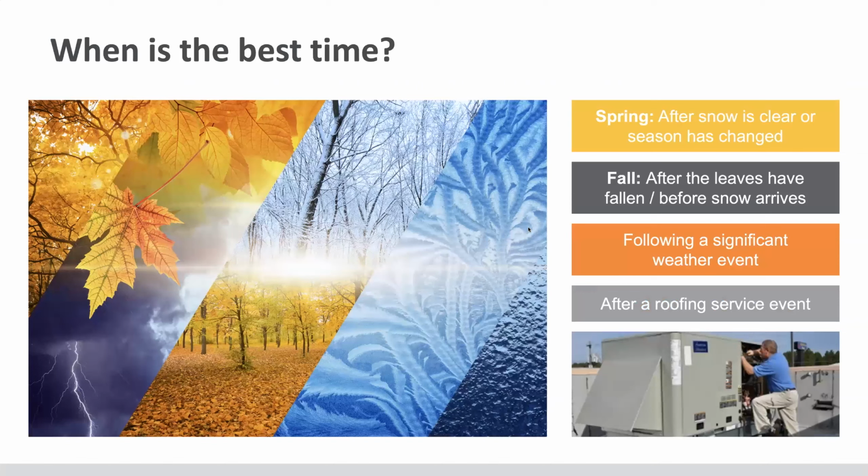The best time we feel to look seasonally is in the spring, especially, I live in northern Wisconsin, when the snow clears, it's really a good time to take a look. Expansion and contraction has occurred, and things tend to pop open, blow up, if you will, and it's good to catch those things on an annual walk prior to the water coming in, those April showers. And again in the fall, if you have snow, before that roof gets covered, clean out the drains, the scuppers, gutters, anywhere we can get the water off that roof quicker.